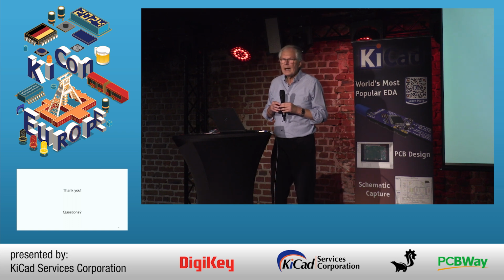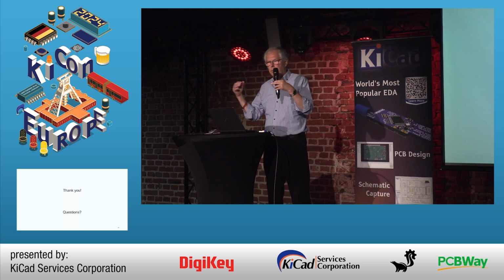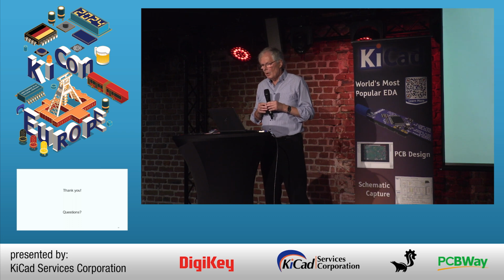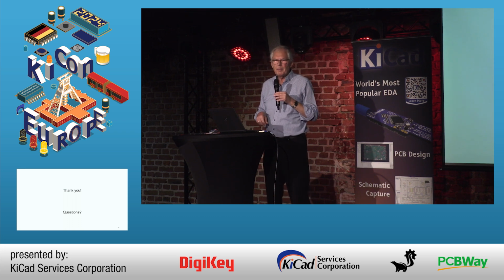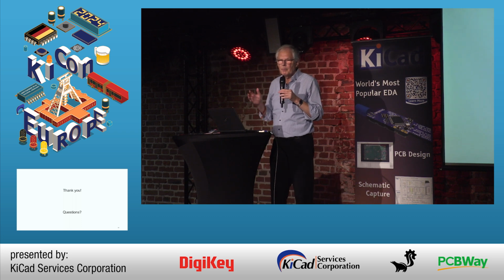What we can do right now is generate S parameters of whatever circuit. So we have two ports or even more than two, and then we just generate the S parameters out of that. What we also can do is S parameter simulation on small signal, sort of AC simulation with S parameters at the building block.